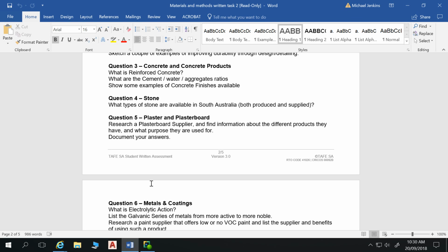Well, certainly it improves it. So if I was to add reinforcing to concrete, what would I add as the reinforcing? The steel. Steel is really good in tension. Concrete's really good in compression. Add them both together, you get this reinforced concrete material that resists bending forces very well.